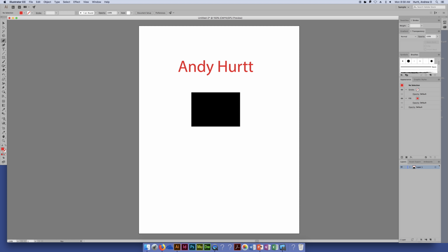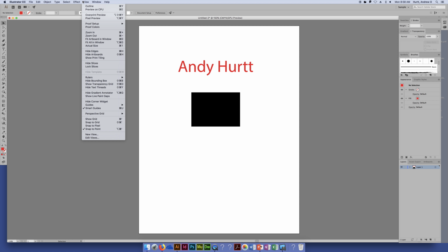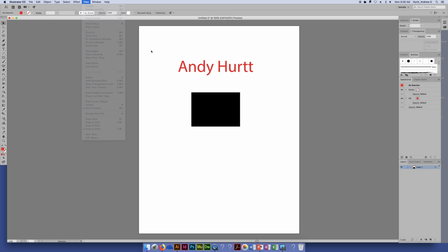So moving and modifying and viewing the artboard, like almost any other application, you have your magnification. You can hit under View. You have zoom in, zoom out, fit artboard in window, fit all in window. If you had like 10 artboards, you can do fit all in window, and it'll bring all the artboards into your window. I tend to use the shortcuts for these constantly.